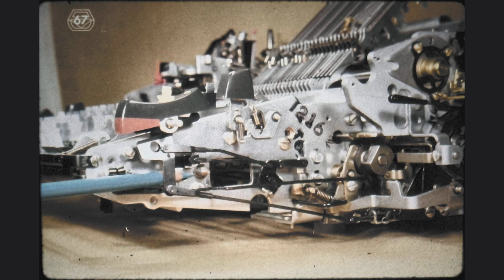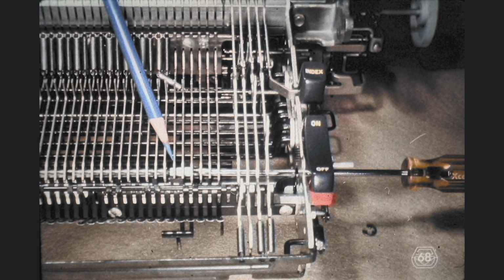Let us now remove a couple of interposers. First, we must remove the indicated retainer or clip. Now use a small screwdriver or any other follow-up wire to push out the interposer pivot and guide shaft until you reach the same position depicted in this frame. Then pull out the screwdriver or the follow-up wire until you clear the indicated interposer plus the interposer located to the right of it. Then pull out the 2 interposers.